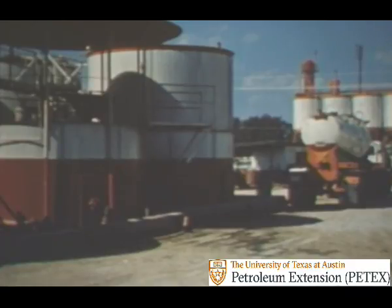After making the decision to use the oil mud, it was decided to mix the mud at the mud company's liquid mud facilities rather than at the rig. Mixing could be done at the rig, but better mixing facilities were nearby and a more stable mud could be made.